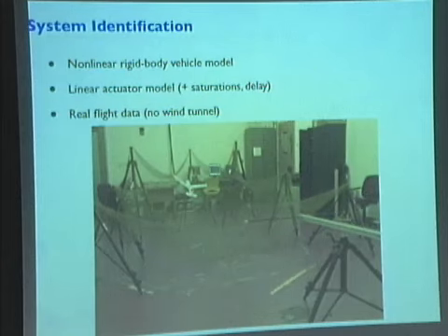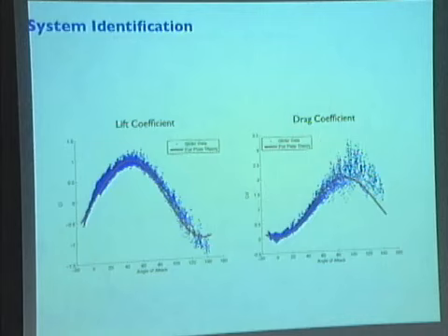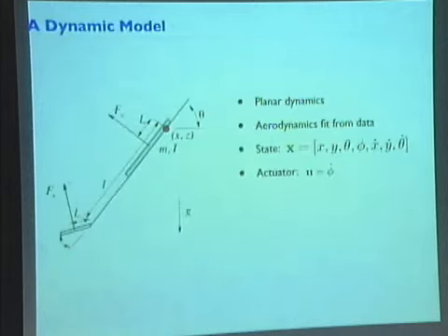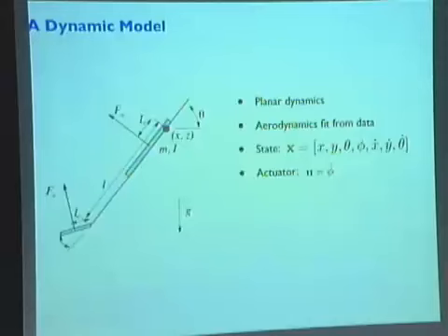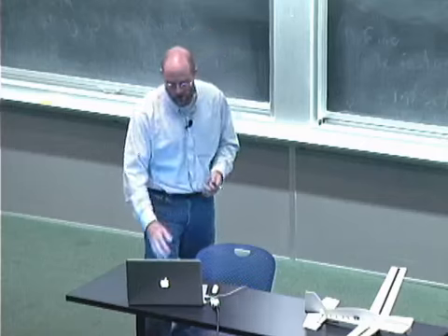We built a pretty good model of the plane, which, for an aerodynamics crowd, is a surprisingly good fit to the lift and drag forces over a very large range of angles. And then we had a 6.003 problem, basically. The nonlinear terms make it a little different. What we did as a group was innovate a way to design a feedback controller that could make this thing very accurate during very high performance maneuvers.